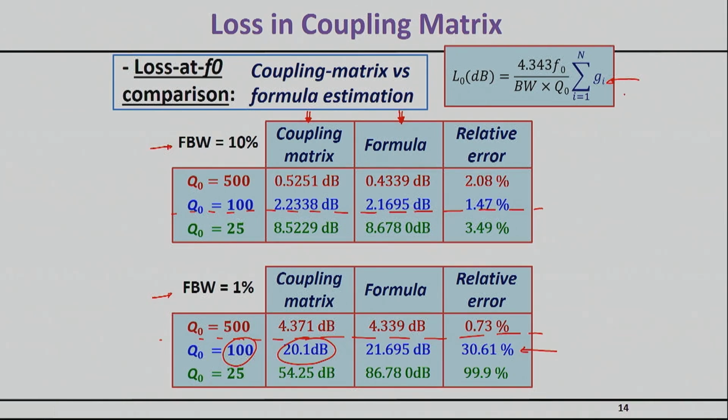But as long as your insertion loss is not too high, in other words, as long as the number you will see here from this graph is maybe between 1 to 5 dBs, you can probably trust this formula, that you're getting something decent.